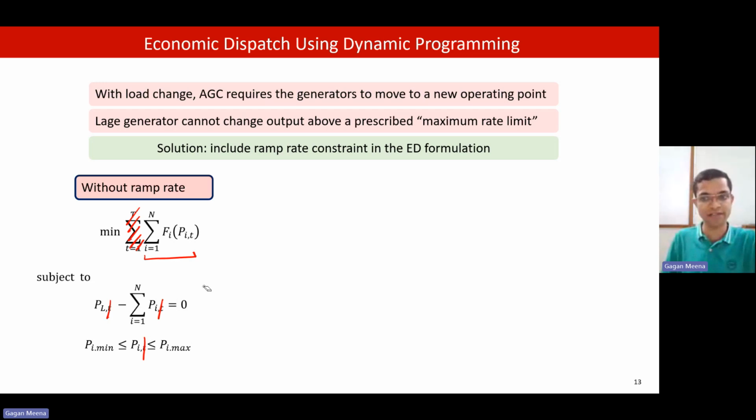But we have already seen that we cannot solve this problem individually because of this coupling constraint. These constraints are called coupling constraints. We see these constraints for the ramp rate of generators, and for storage also. We'll see that for energy storage. We have already discussed one kind of energy storage, which was pumped hydro energy storage. There are SOC update equations or energy update equations.